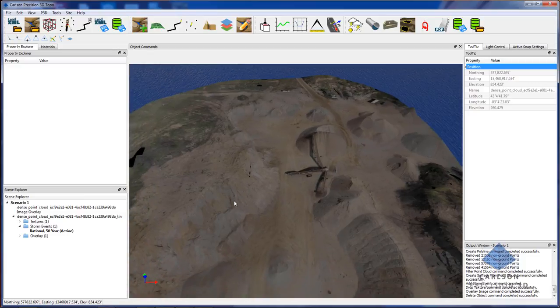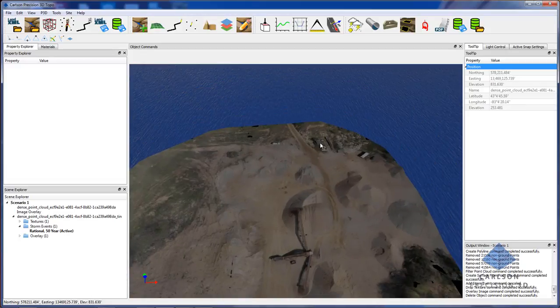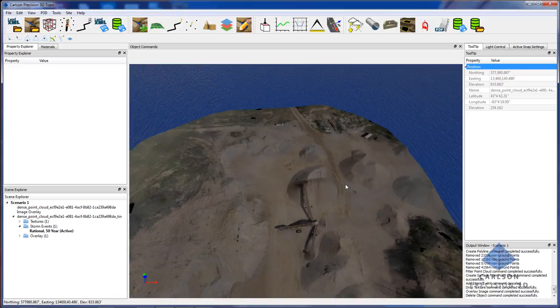And there you go. Using polygons to constrain the Bareground algorithm, which can take a long time to run. And by a long time, I mean a few minutes. But if you constrain it to areas where you know that you want to work in, you can use different settings. So I can draw a polygon here, and I can apply different settings that are more optimal for removing this machine than for removing cars, which are a lot smaller. So you would use different parameters for that. And by using the polygons, you could basically apply different parameters.